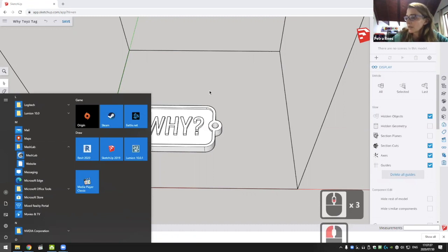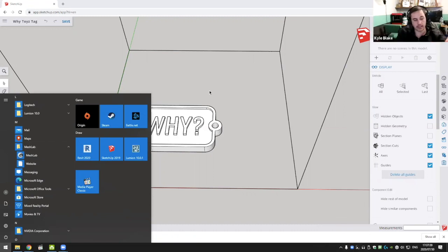So what MeshLab does is you import it because it has no problem handling all those faces, and then you can actually go and clean it up. Sometimes, like with that little squirrel, when I imported it, it had over 100,000 faces, which SketchUp was just not willing to handle. And I managed to reduce it down to about 6,000 without losing any of the quality. It is a very complicated program, and I only know how to use it just to simplify the models, because it can do a lot. But yeah, for simplifying models to bring back into SketchUp, awesome.